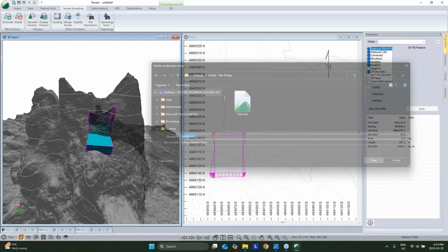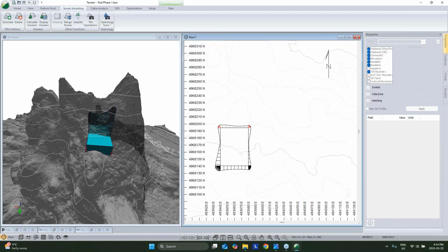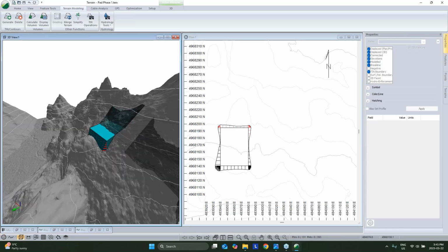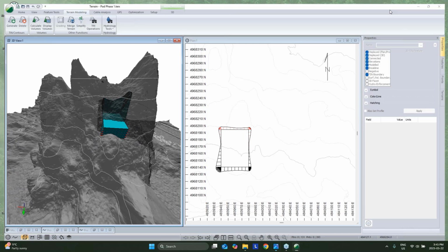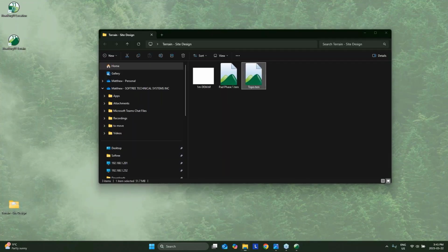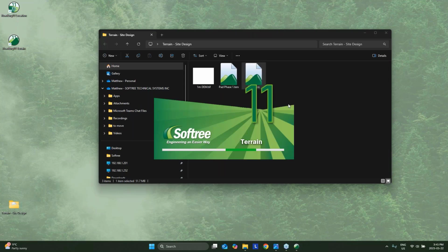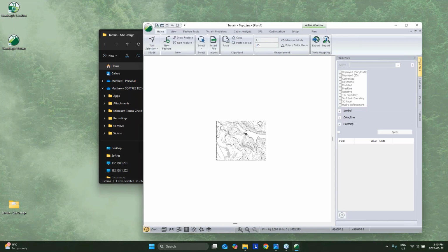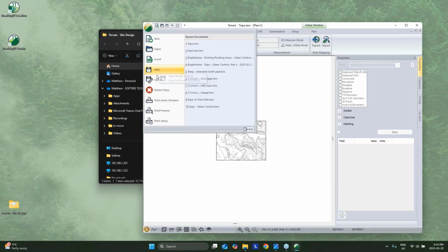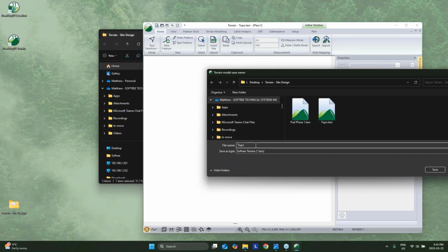And I wanted to, well, maybe build that in 1 year and then come back in here and build out from it later on. But I wanted to account for the surface following year 1 construction. We could do a merge. So for that, I'm going to create what we refer to as a composite surface. So in my topo, I'm going to first change the name, topo with P1.